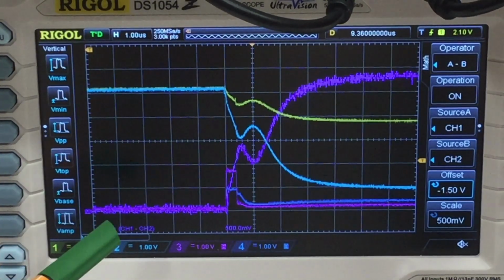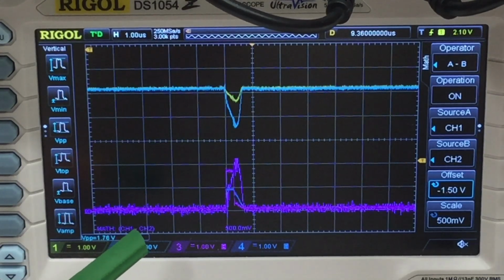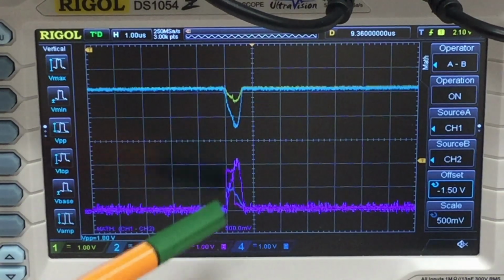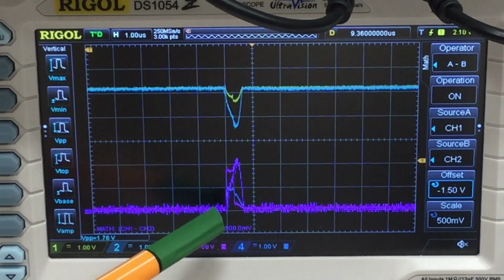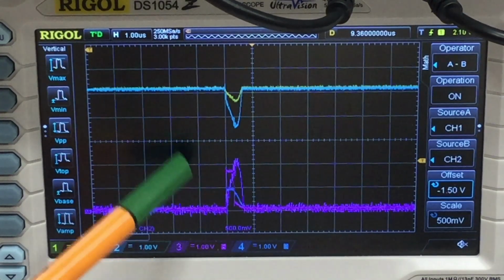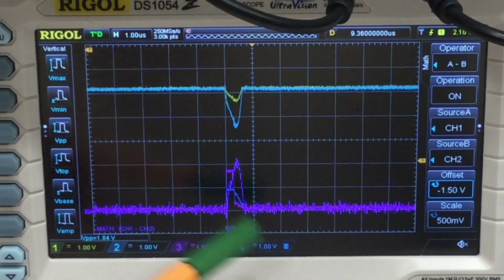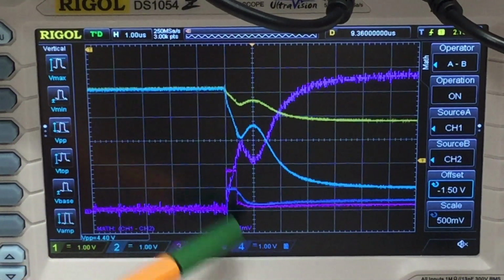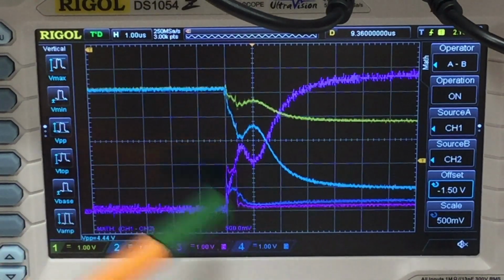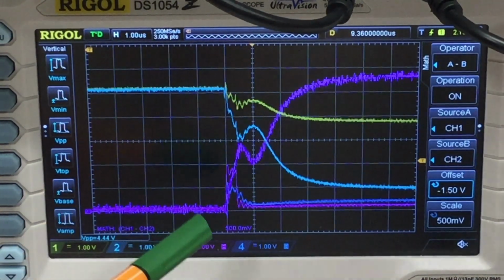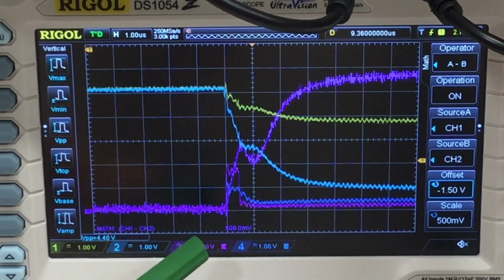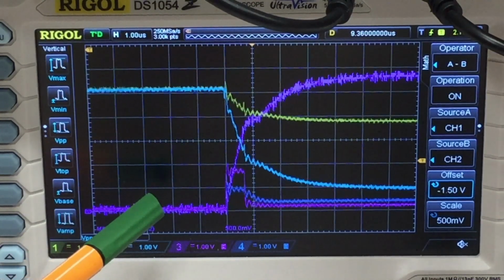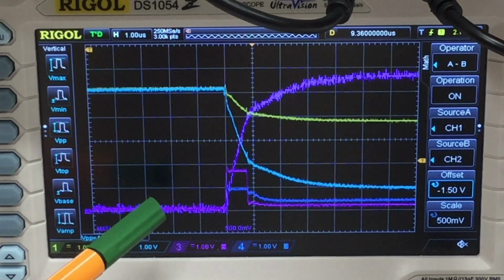Now we get some weird effects. We are now at 0.3 microseconds. And the trigger pulse gets too short to get the thing reliably in the on state. And even if it's 0.4, that's not a nice switch on. 0.5, 0.6, 0.7. Okay, then it's getting better.